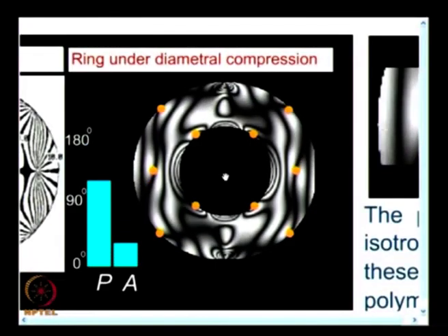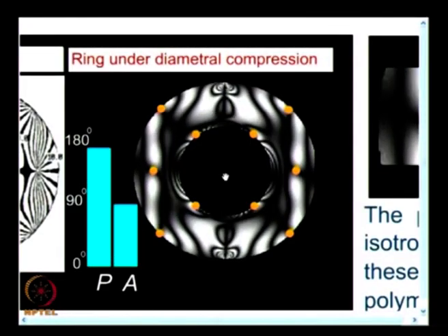Do not look for more isoclinics to pass through in every 0th fringe order. There are special situations. The special situations are what you see in a beam under bending and disc under diametrical compression. These are exceptions. You should not mix up exception with a general rule. It is good that you asked that question. It is a very valid confusion that you can come across.